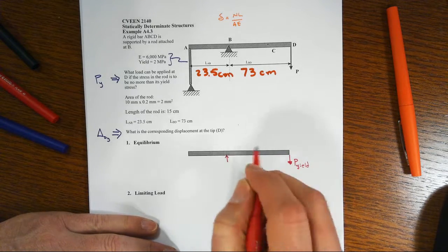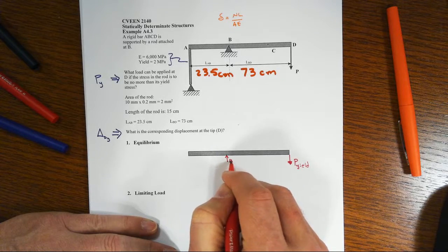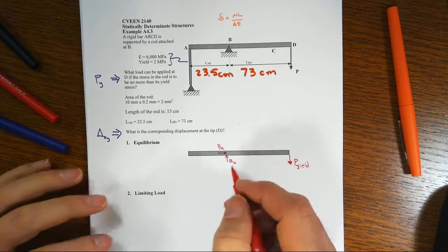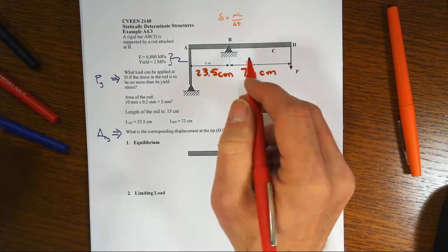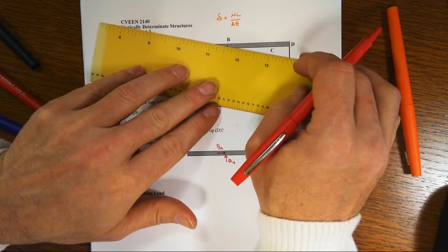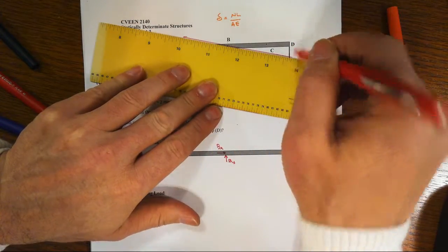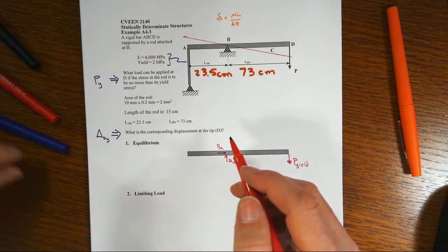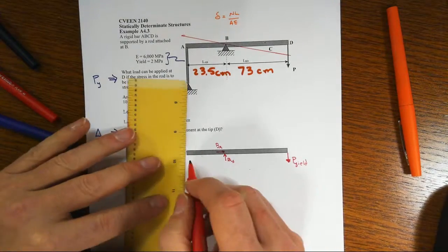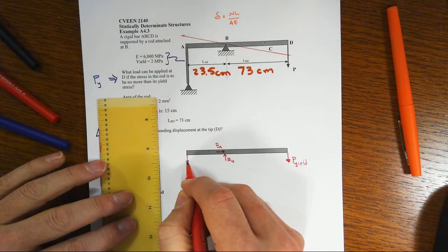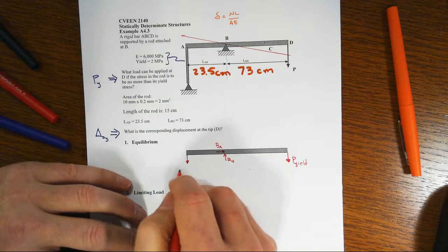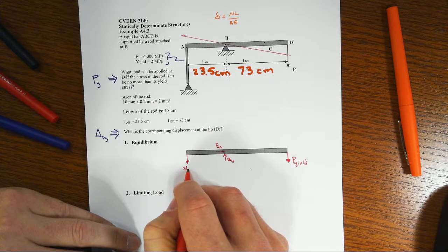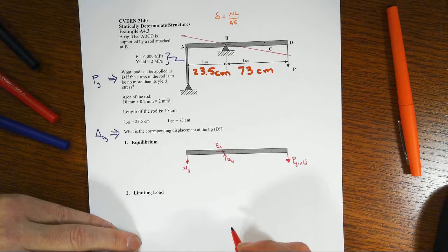Then we have our reactions at B, and there possibly could be two, one in the X and one in the Y. With the given system, if it's going to rotate in the direction of the load, it will extend the rod at A, meaning that rod at A is going to want to pull back on the beam, and there is your axial force in our rod. We might call that N sub Y since we're at yield.